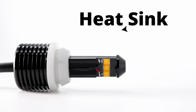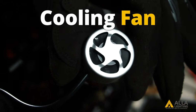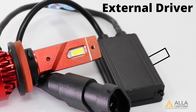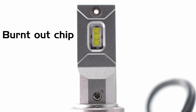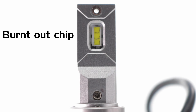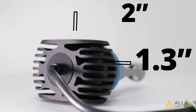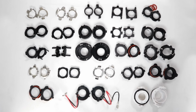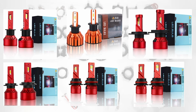The second cause, the heat dissipation system is too big. No matter what kind of heat dissipation your LED headlight bulb has, fanless or with a fan, LED headlight bulbs require a heat dissipation system that stock incandescent bulbs do not, because LED chips cannot withstand the heat as well as incandescent bulbs do. In fact, heat is the major cause of LED bulb failure. Thus, the brighter you want, the larger heatsink you should expect. The third cause, adapters are required, which is very common among H1, H3, H4, H7, 9004, and 9007 bulbs.